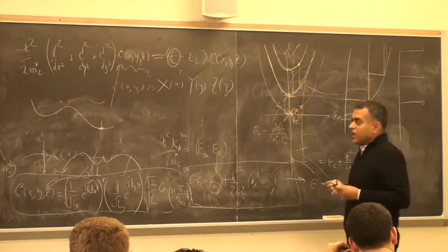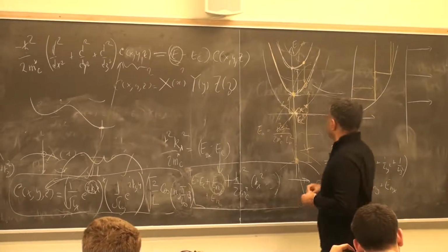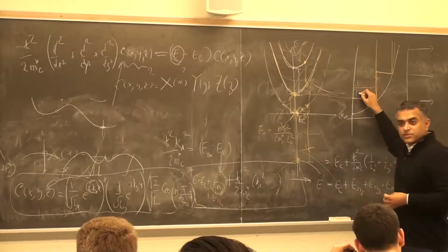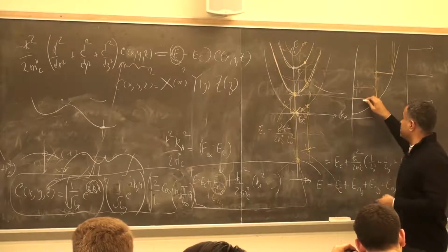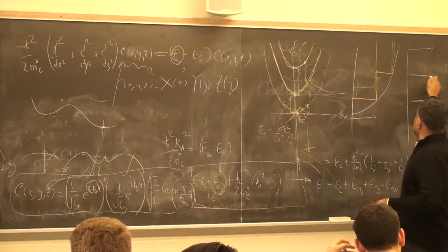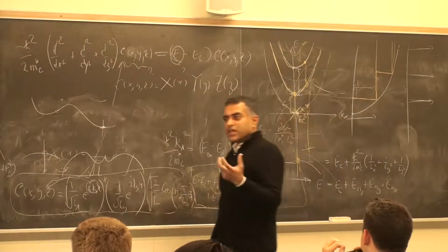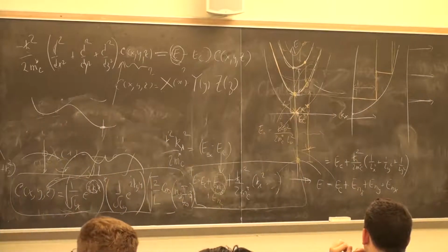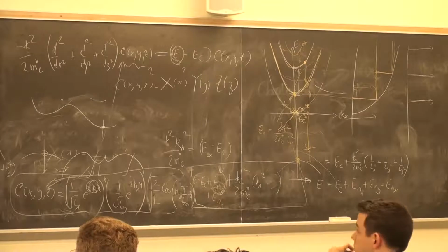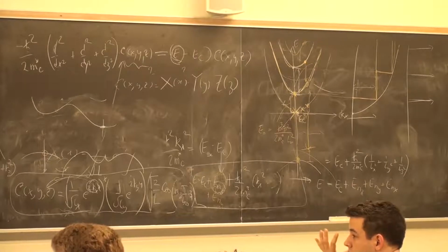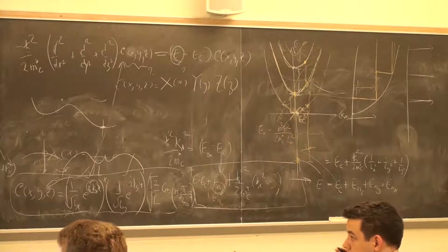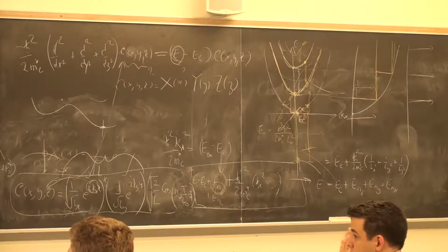So only when you have free motion in some direction can you have a continuous DOS, which is non-zero. The moment you go to confinement in all three directions, that thing looks like an atom, which is not a continuous density of states. It's discrete energies now. So that's going to have less effect, because very few electrons can occupy any of those bound states if it's really atom-like.